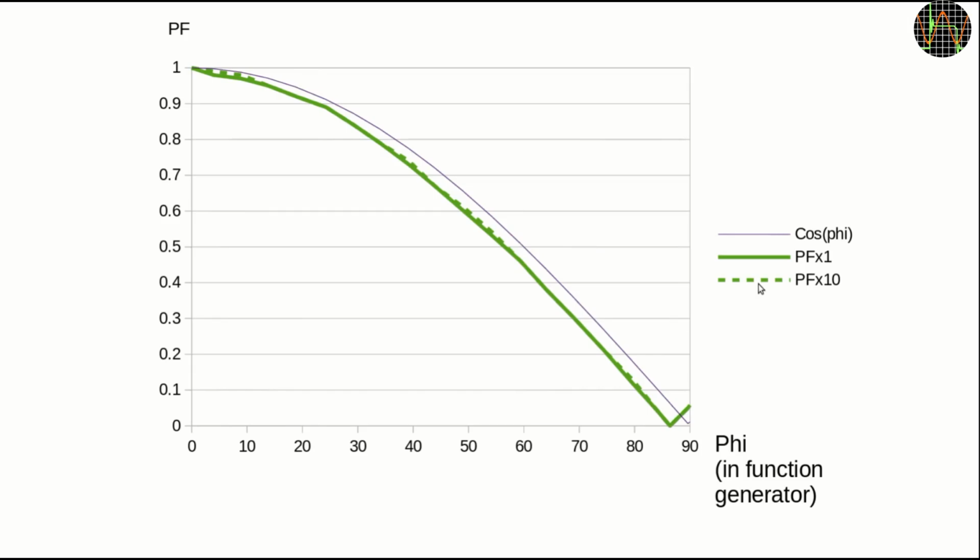The key point is that it first needs to calculate power, which means it needs an accurate current, and as I have shown, the current measurement isn't better than 1.5%, and the lower the power factor, the less active power is remaining for that calculation, which explains why the trace is close to the theoretical value at high power factors and deviates more at lower power factor values. For now, let's just say its reported power factor in this test is certainly within the ballpark and usable, even if the promised 1% are not reached.